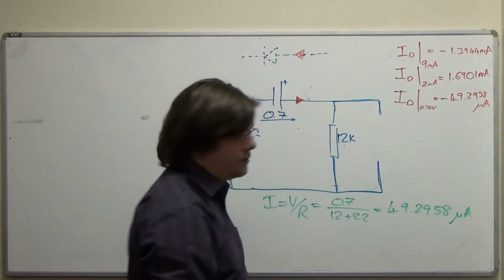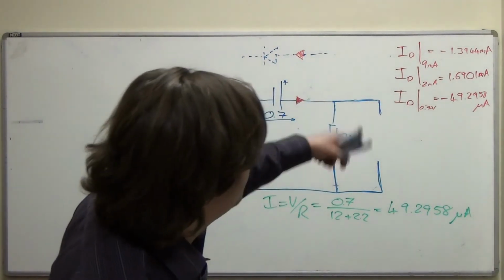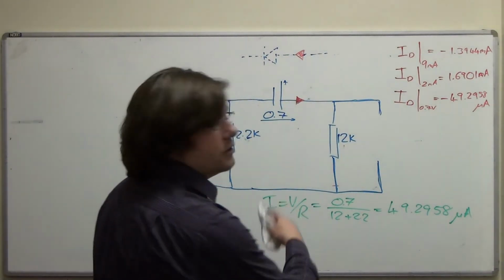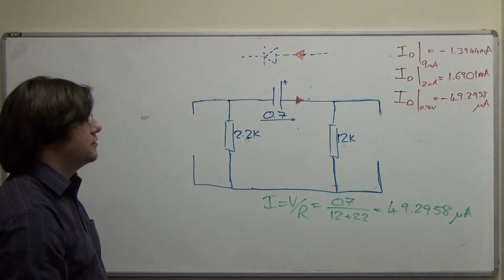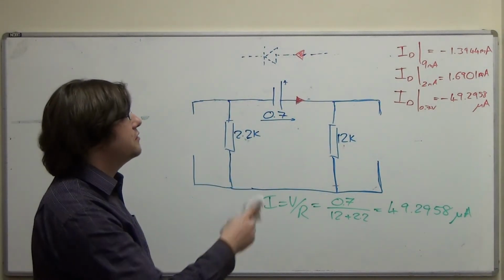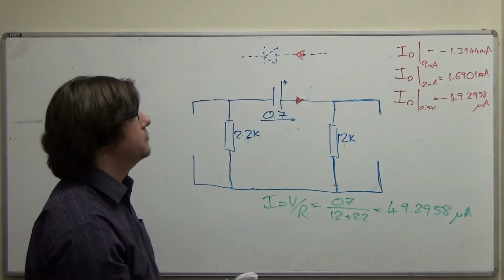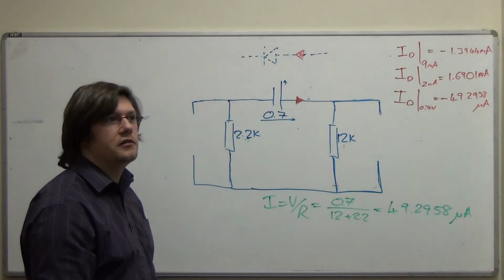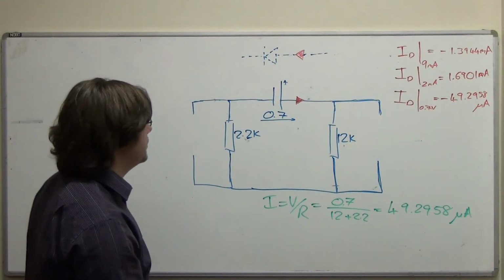So then I've just got to add up my three values, and I do just add them. The reason I just add them is because I've already got the minus signs in place, and that's why it's so important to make sure you get your signs right, because otherwise you'll be adding up currents that actually should be subtracted from each other.